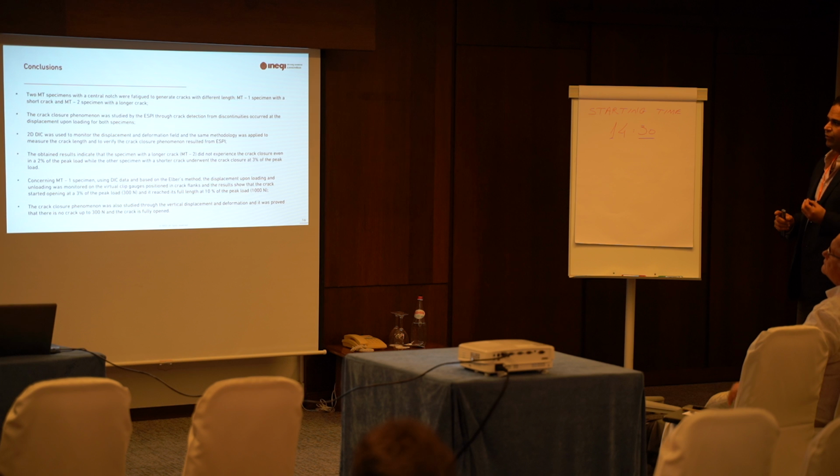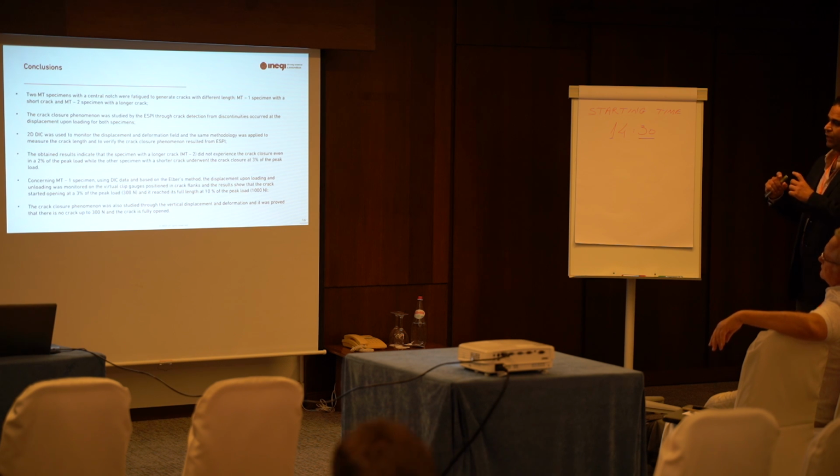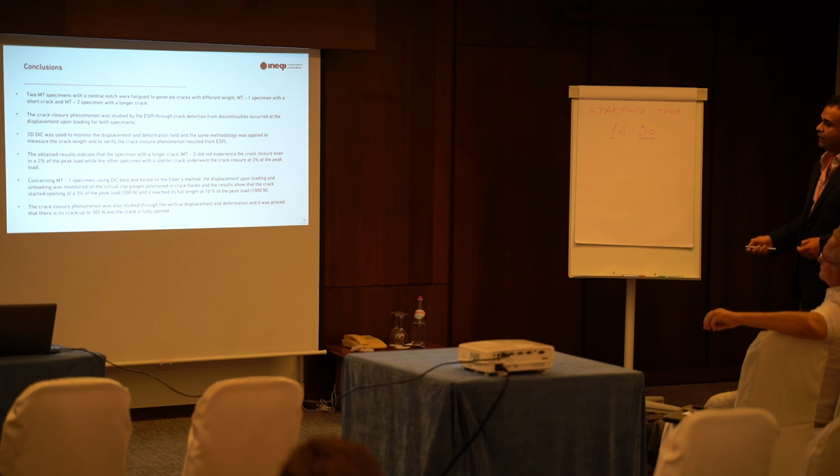The scenario is the same with digital image correlation, but DIC was a better approach in order to follow Elber's methodology: putting virtual clip gauges on the specimen, then loading and unloading it with the same sequence and obtaining the force-displacement. Then the minimum load, which is 3%, 300 Newton, gives the local closure and opening, and 10% of the peak load, which is 1K, gives the full crack open.